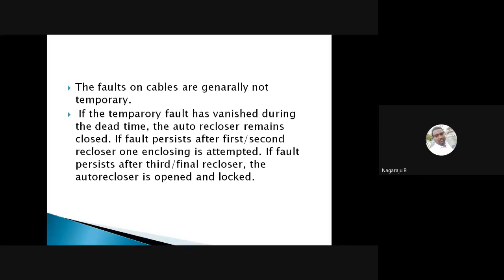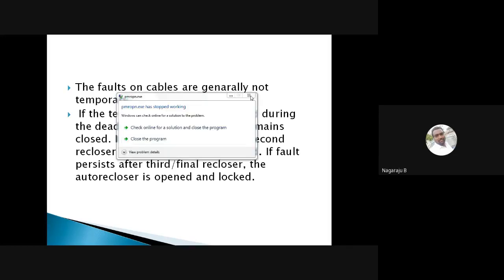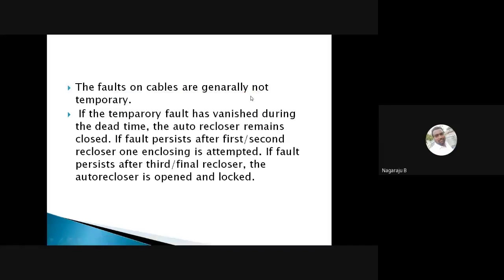Okay, and a recloser is made up of an interrupting chamber and the related main contacts which operate in oil, and a control mechanism to trigger tripping and reclosing. Reclosers are designed and built in either single phase or three phase units.